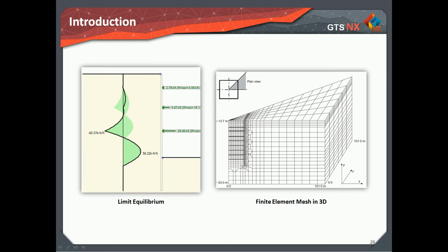Until recent years, the analysis of retaining structures has been done by simplified methods such as Rankine and Coulomb method or traditional limit equilibrium method, which are based on conditions at collapse when the full strength of the soil is mobilized. Limit equilibrium calculations do not in themselves give any indication of wall movement, although some computer software consider the interaction between the wall and the soil to provide some suggestion of wall deflection.